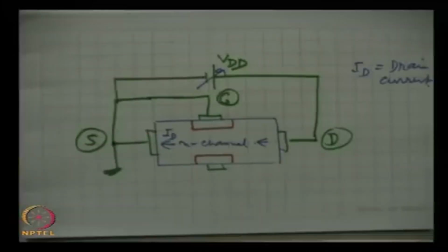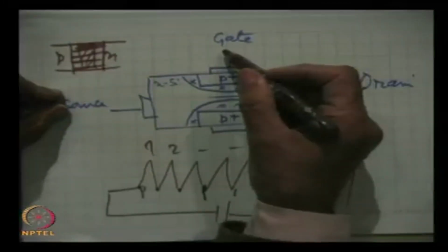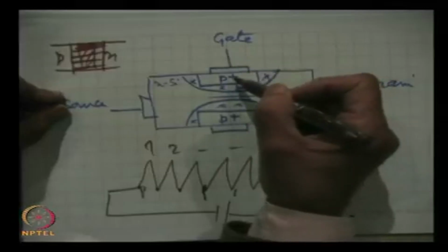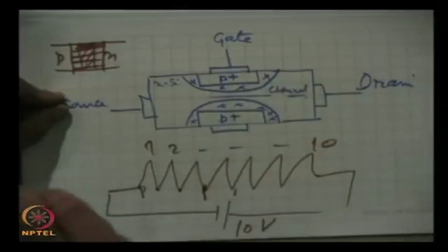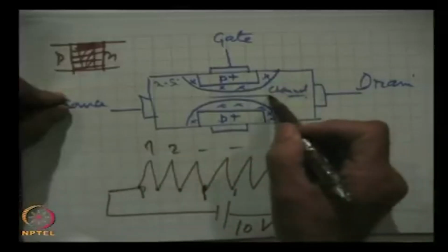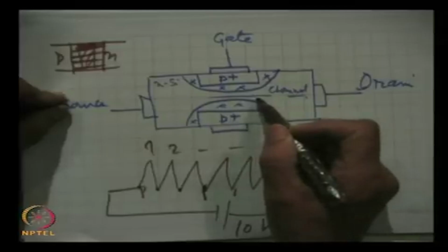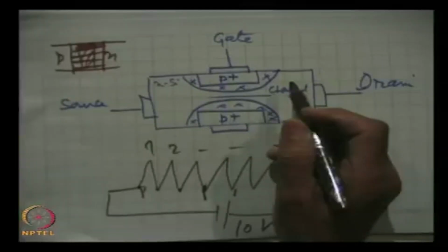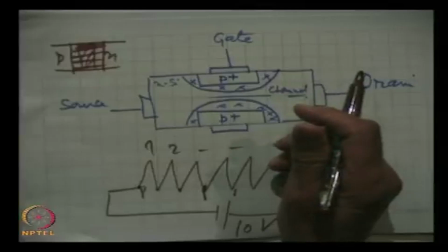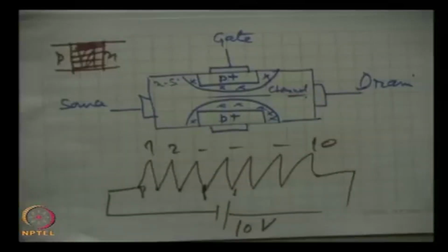Now, we can reverse bias the junction either by giving a negative potential to the p type material, or, very important, a positive potential to the n type region. I repeat, we can reverse bias the p-n junction by providing, suppose one is grounded, a p type negative, more negative with respect to that grounded terminal, maybe n type, then broadening of the depletion region will occur.